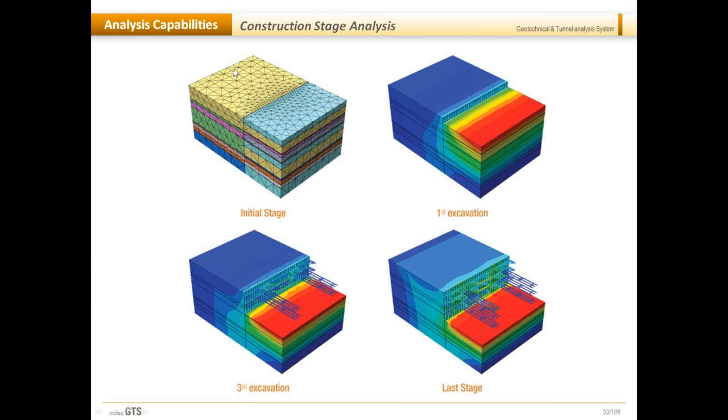Let's begin with the construction stage analysis. MIDAS GTS is very practical to define such kinds of construction stage projects, because there you can use construction stage, seepage, slope stability, and for each you can use the construction stage. You can obtain the in situ ground conditions for the various soil layers. Then you can activate and deactivate the boundary conditions and the loads. You can use the wizards to automatically define the stages and simulate and really capture the real construction stage sequence.